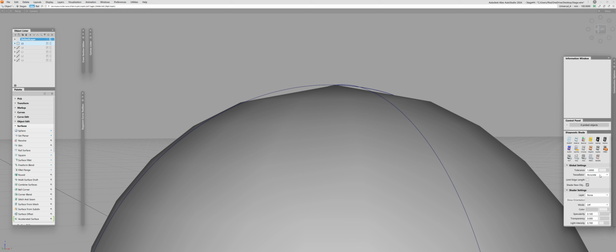I guess at this point you add 2 and 2 and have already figured out where it's going, right? So let me make a big reveal until it completely spoils. What you're looking at in Alias is not a NURBS geometry. It is a mesh, a polygonal model. And it is not only true for Alias, it is true for every single CAD system in the market. You never see NURBS geometry, you see mesh instead.